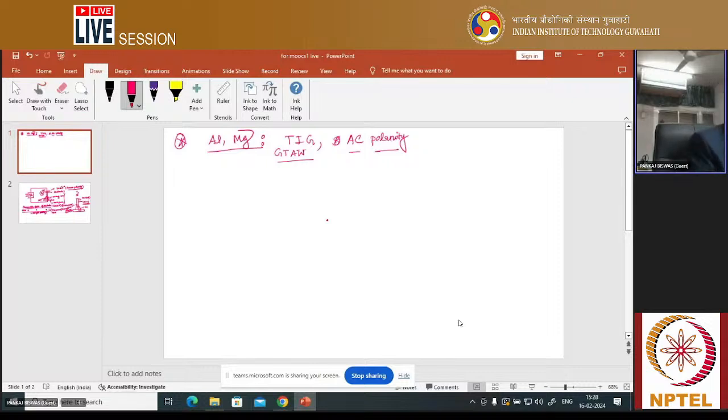Here one thing you should keep in mind. Aluminum and magnesium are highly reactive materials, because once you keep this material in open weather, within a fraction of a second it is oxidized. Let us consider this is an aluminum plate. If you keep it in open weather, a shiny layer of oxide forms over the surface exposed to the atmosphere. This oxide is also called alumina, Al2O3.